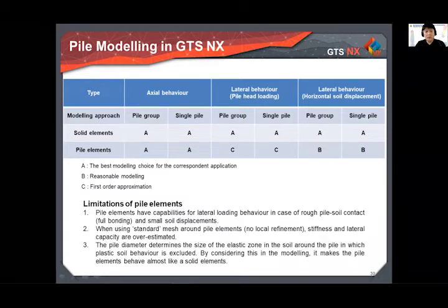It is known that the pile beam element is typically suitable for the axial behavior compared with the solid element, but in the case of lateral behavior, it is expected that it is better to use the solid element rather than the pile beam element.